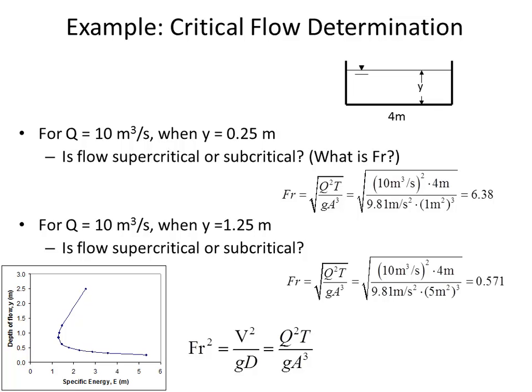It'll pool more, but it finally reaches equilibrium again when it can get enough over the obstruction, and it'll be flowing at the critical depth when it does that. And so you will have E minimum as it flows over that obstruction. That's a real-world example that's very important. We'll talk all about that later, but that's your sneak peek of why minimum flow energy is important to us.